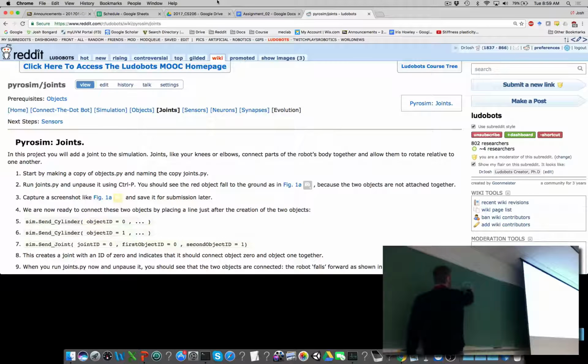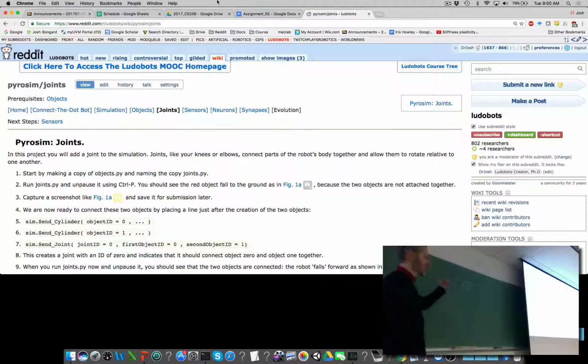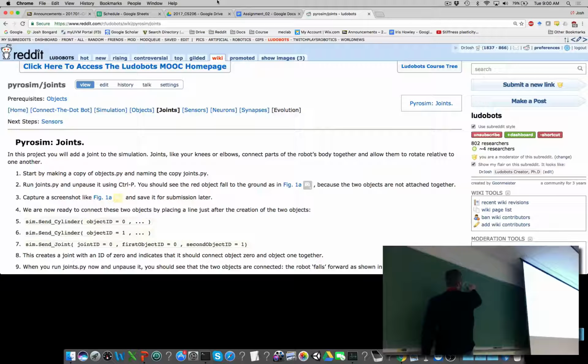And I might give it a normal that points towards us into the screen. I then create a second joint at the same position that connects C3 to C2 and give that a different joint normal. And now I have these two joints which allow, I guess I'll have to do it with my shoulder joint here, right? So it allows this motion and this motion. So in essence, this object can move this way relative to this object.